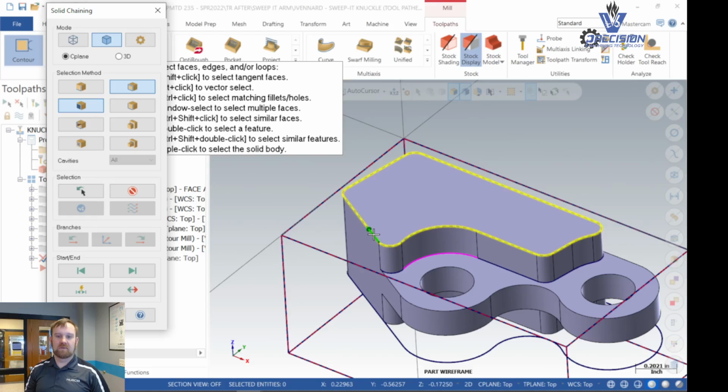How can I not click the... Okay. I can't click my... Go back to solid. You've got to switch your mode to solids. There you go. Switch your mode back to solids and make sure you're on your solid edges. Probably don't want face turned on. You should be able to pick that top edge.